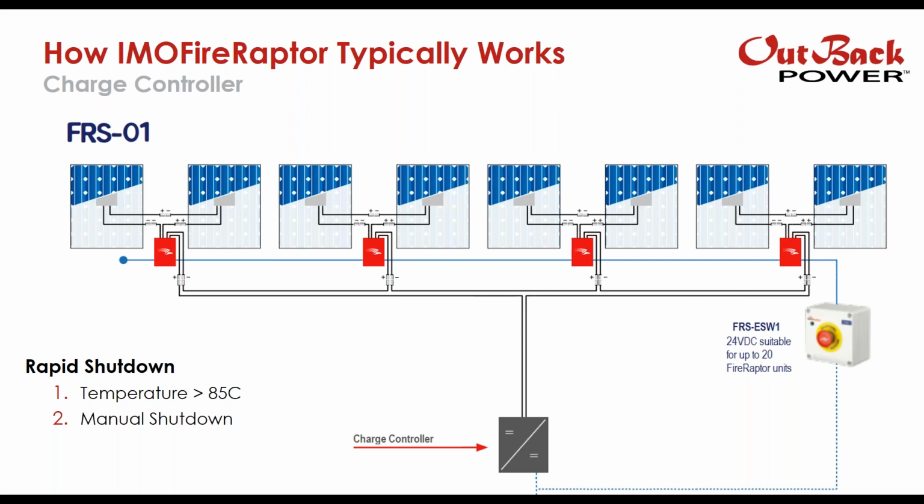All right, so here we have this energy being fed essentially by the batteries. But you really have 2 choices in a battery-based system on how this power is supplied. You could choose the battery, which we have shown here. If this was the case, you would have a DC to DC converter inside here, right? Because you'd be converting 48 volts, if you had a 48 volt system, to 24 volts.